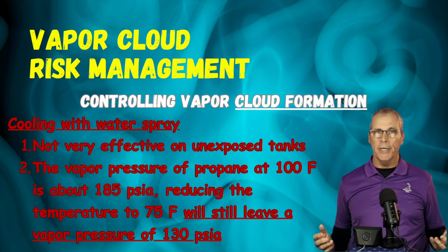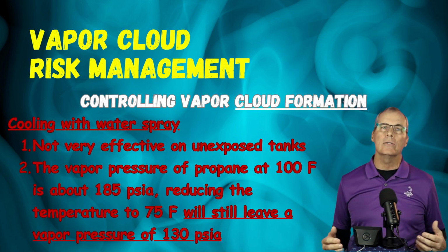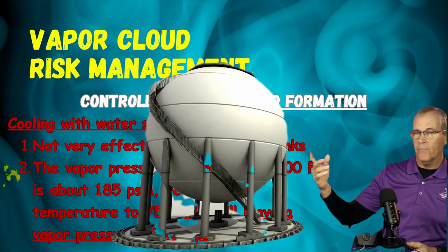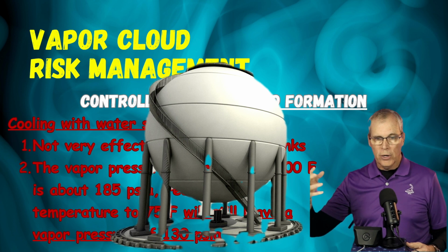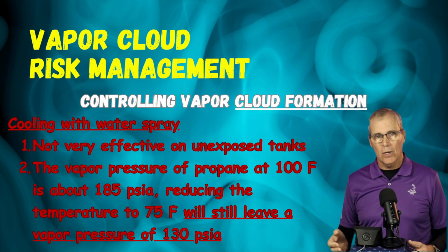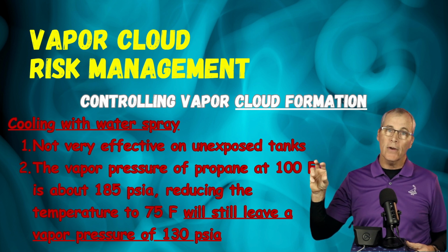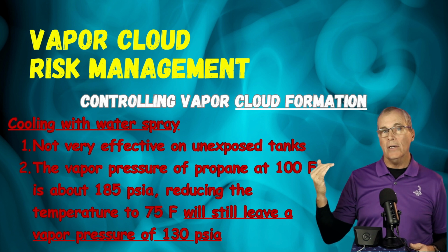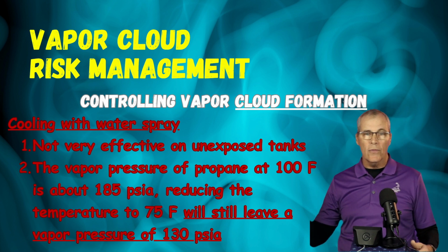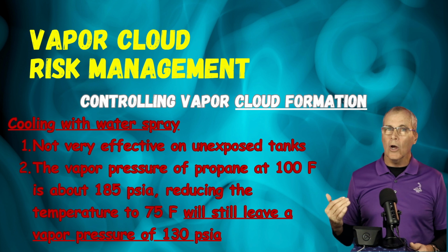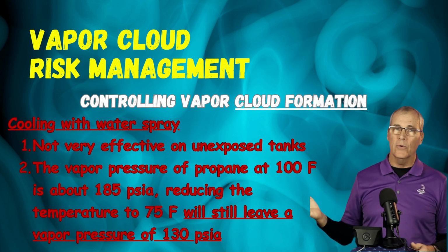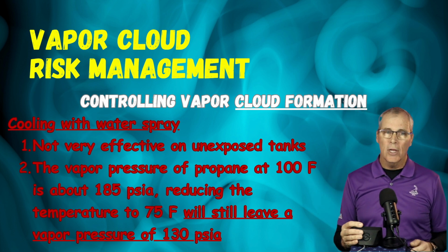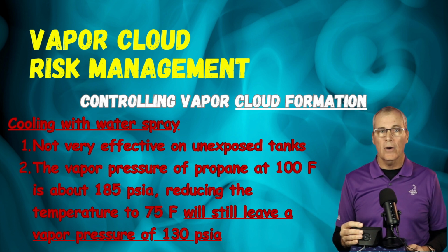First, let's talk about cooling. Let's talk about a propane tank that's got some heat, maybe some radiant heat from a fire across the facility, and we're worried about the buildup of pressure. Well, if you take a tank from 100 degrees Fahrenheit to 75 degrees Fahrenheit, blowing water on it, you're really only dropping the pressure in there from 185 to like 130 psi. So you've still got quite a bit of pressure, and you've exhausted a lot of resources and a lot of water spraying on a tank that isn't really involved. So that's not one of the things that we would put as a top priority.